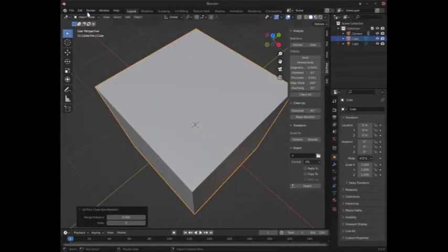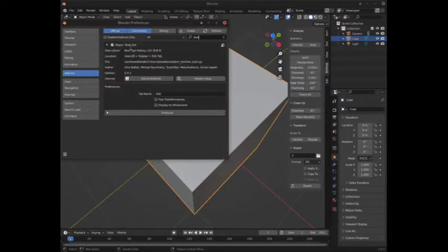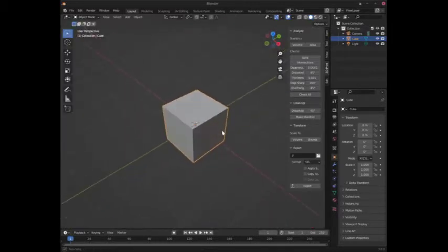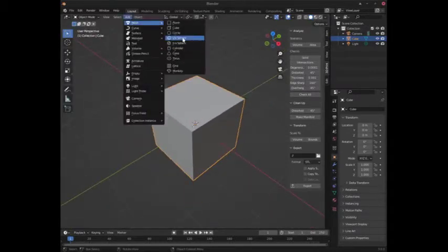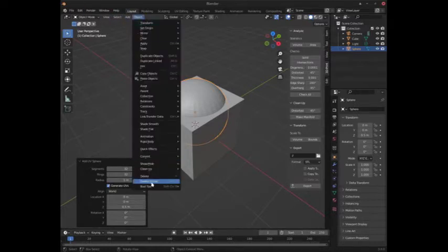The second tool that you're gonna need is Bool Tools. And what this does is making Boolean operations a little bit easier on you. So let's say we got our cube, yeah? Let's add a UV sphere. Move that up, just like so, and we'll set it right there. We'll add a few more rings, put that up to 32. And now, with Bool Tools, you go to Object and then Bool Tools, and then you can do your auto